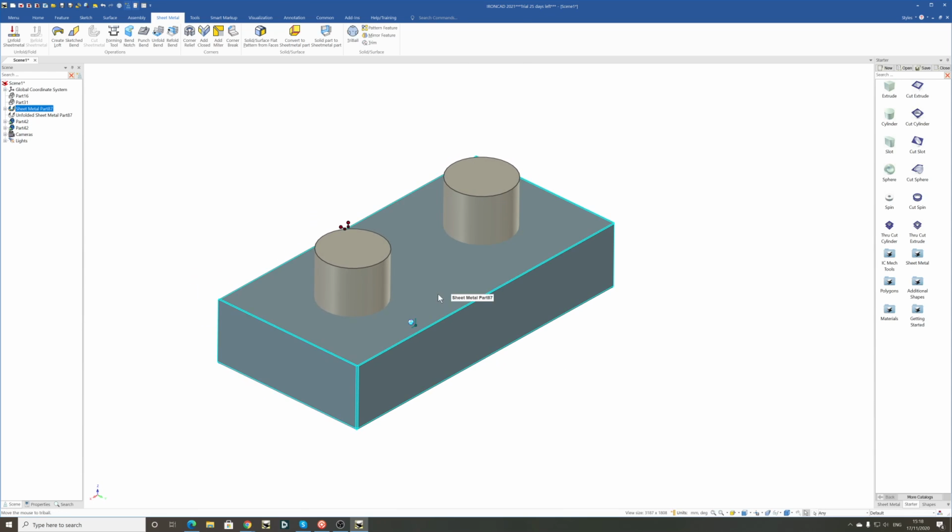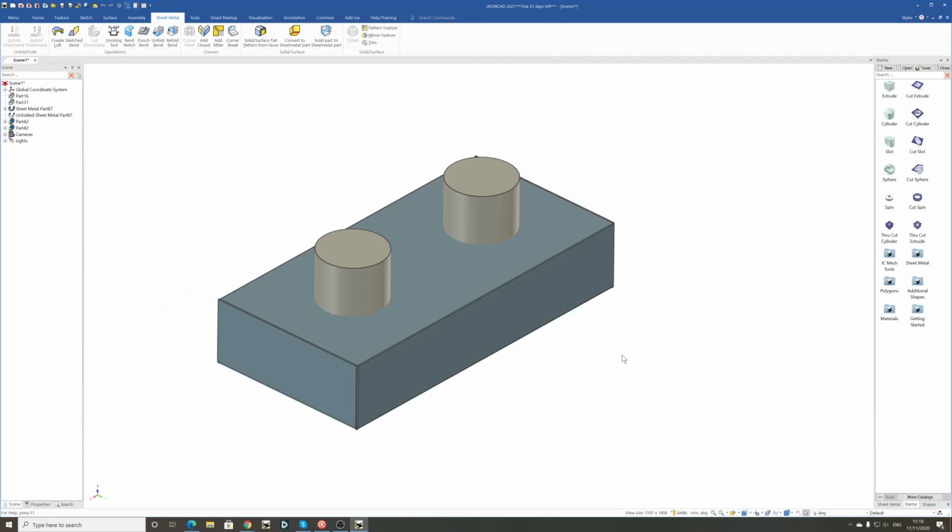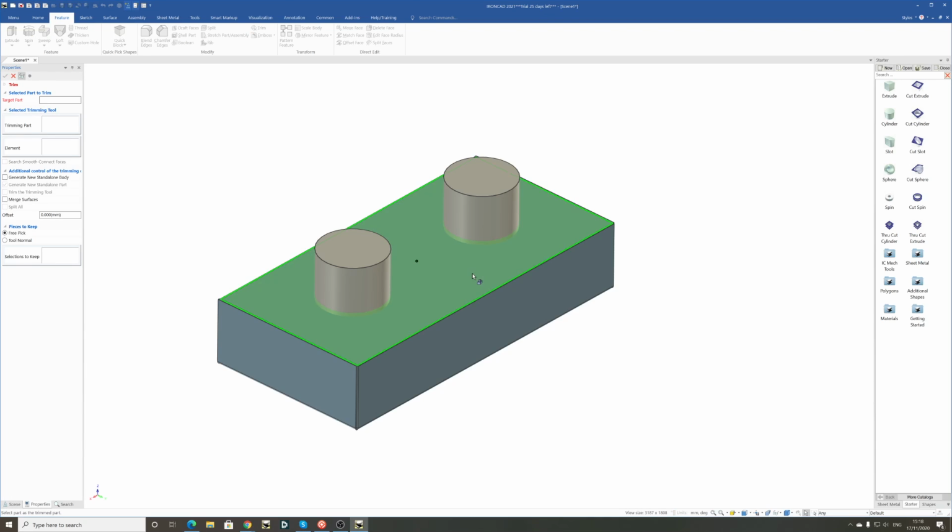That's just 2 cylinders, because if I unfold it, you can see that those holes are not gone through because I've not done anything to that sheet metal. So what I can do is go to our features and click on the trim. You don't have to work out on the developed shape all the sketches and the dimensions to the edges and everything, because it all becomes quite messy. You're just working in a free-form environment, which is where you want to work.